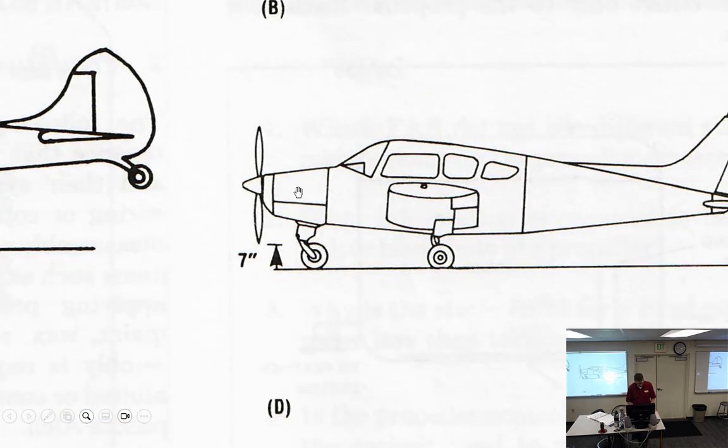Minimum of 7 inches between prop tip and ground. Now you've got to think about it. We have struts, people in there, fat people, thin people, fuel loads. So it's at taxi takeoff position with gear statically deflected, which means a load on it. Static deflection is simply the amount that a spring compresses under the weight of the equipment. Only a positive clearance is required with a strut deflated and critical tire blown.